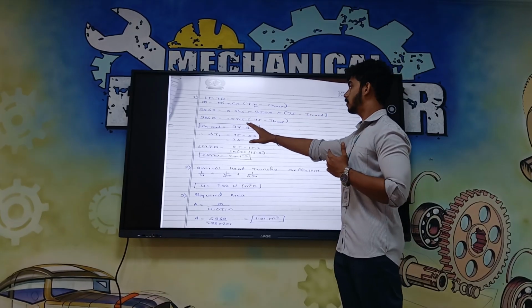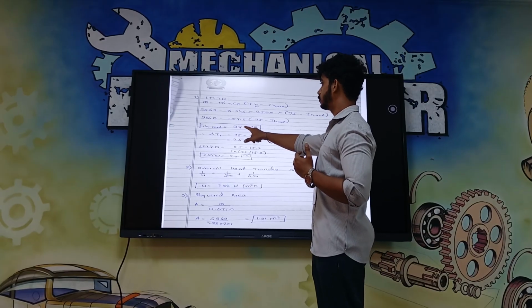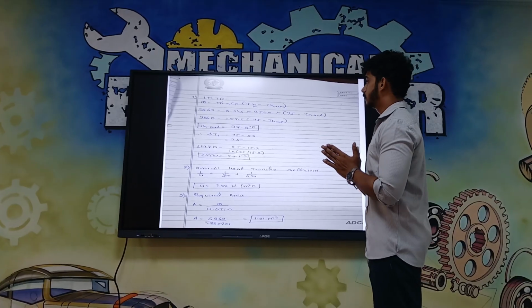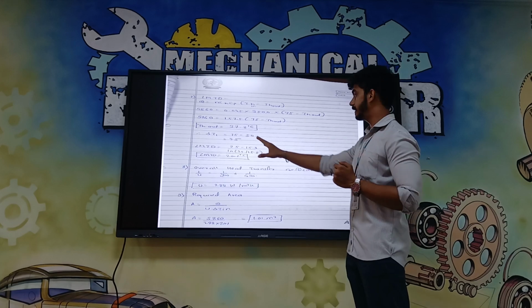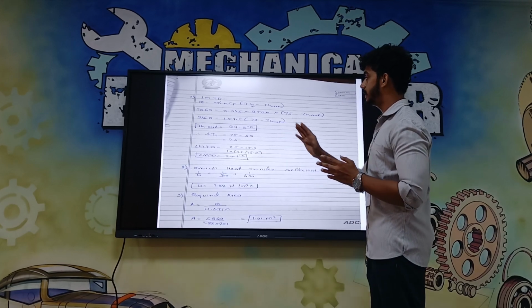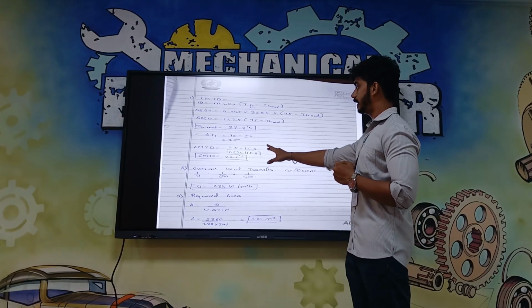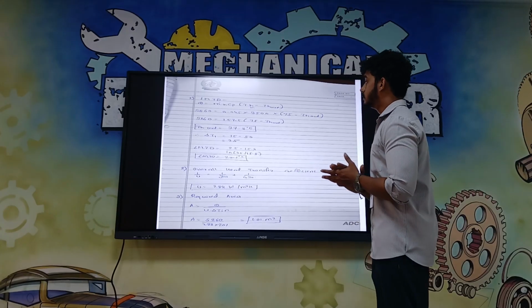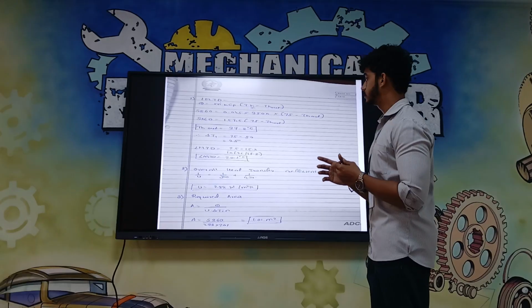So T_H out is 37.8 degrees Celsius. For delta T1, we have 75 minus 50, which is 25 degrees. Later the LMTD is delta T1 minus delta T2, that is 25 minus 15.8, divided by ln of 25 divided by 15.8.